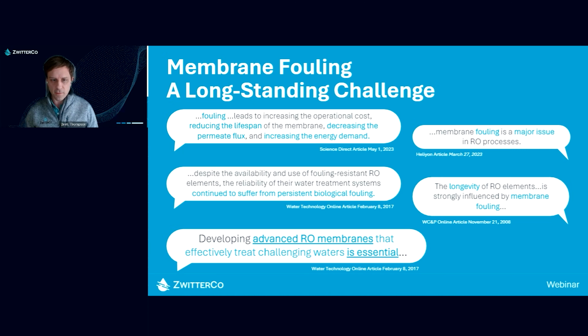Typically, these consist of a coating on the surface of the membrane that helps prevent fouling, but could eventually wash off of the surface. Or they use advanced feed spacers that might have unique geometries or wider openings. But ultimately, these can also still be subject to irreversible organic fouling.